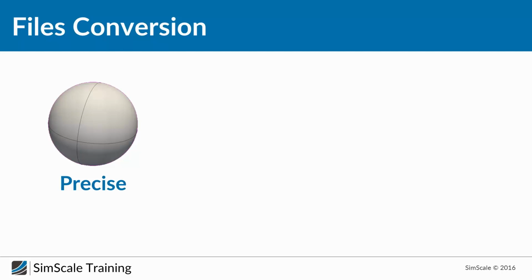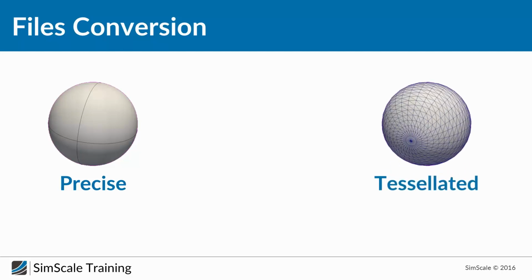Now, one of these formats is the STL, and it's a really good format to handle, especially if you have a high quality surface. So when we start from a precise surface, from the CAD point of view, when we design this part, we can convert the precise surface into a tessellated surface. It's possible to do this step in any CAD software available in the market.